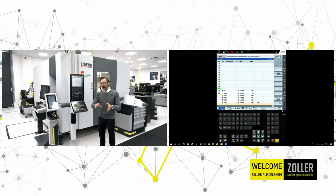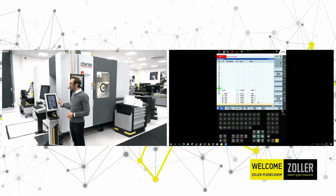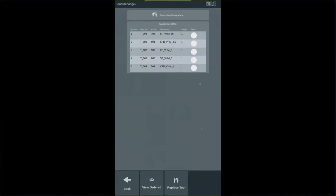So what we are doing now is we are loading the tools into the CNC magazine on the back side. We're producing our workpiece. Maybe we have to do it several times, maybe 50 times, whatever. And then the operator recognizes, oh, there is one tool which runs out of lifetime or is short to, we need to replace it. And for this, we have a very, very nice function which is called tool exchange. So right here from the machine, we have the possibility to perform this tool exchange.